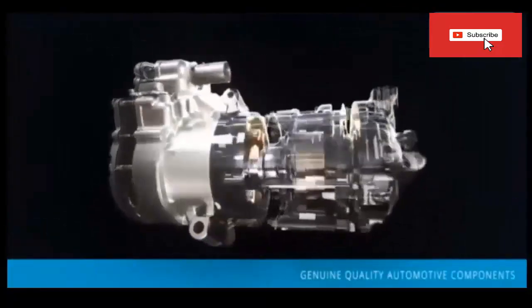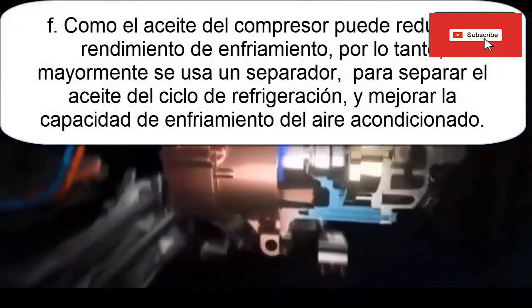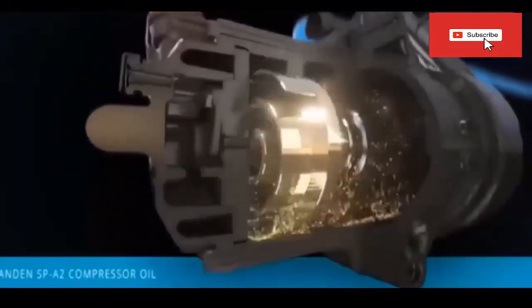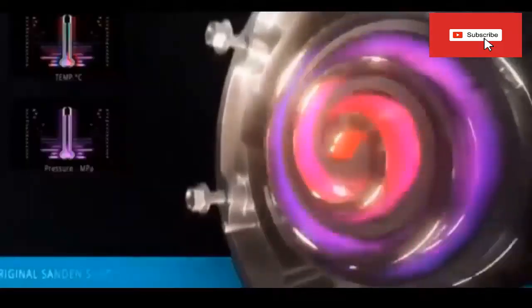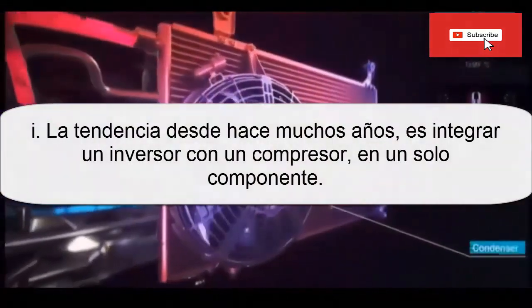F. As compressor oil can reduce the cooling performance, a separator is mostly used to separate the oil from the refrigeration cycle and improve the cooling capacity of the air conditioner. G. The electric motor works with a high voltage of 200 or more. To insulate the electric motor and the compressor casing, compressor oil with high insulating properties is used. H. The trend for many years is to integrate an inverter with a compressor in a single component. I. The controlled speed of revolution contributes to energy savings.